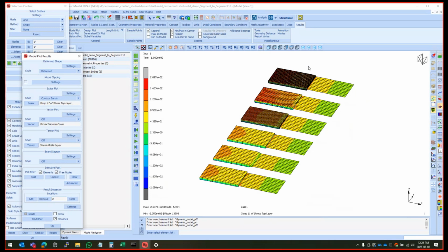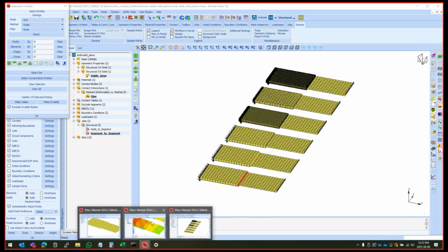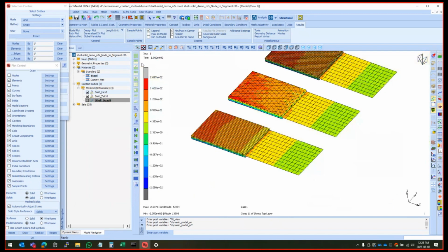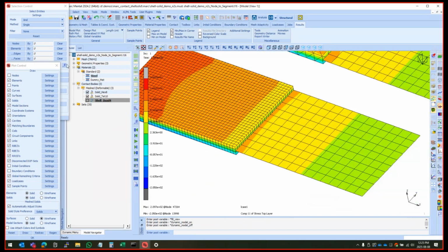Another comment in the chat I wrote is the dummy thickness, what if the dummy thickness is not 1 millimeter, but 1e minus 5? So it's very, very thin. Have you experienced singularity in those elements? In theory, it shouldn't make a difference. I can quickly do a test and show you. And the reason why I don't expect it to become an issue is because the stiffness for those elements are actually fully defined by that rigid and connecting to these.